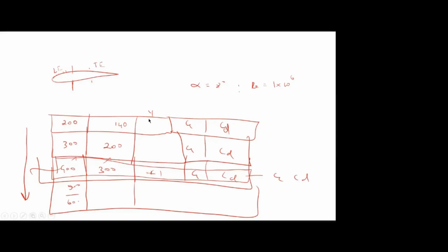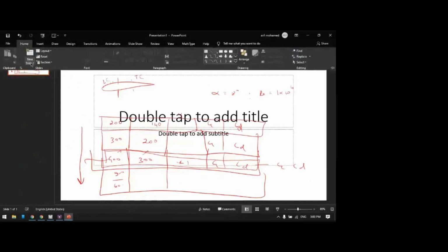To avoid that kind of scenario, there is one precautionary method. Once you save the IGS file of the domain which has been built, you need to reopen that IGS file alone in CATIA again, not the CAT part, the IGS file. Now suppose there are six phases in your domain, then you should have only 6 phases in the main tree.